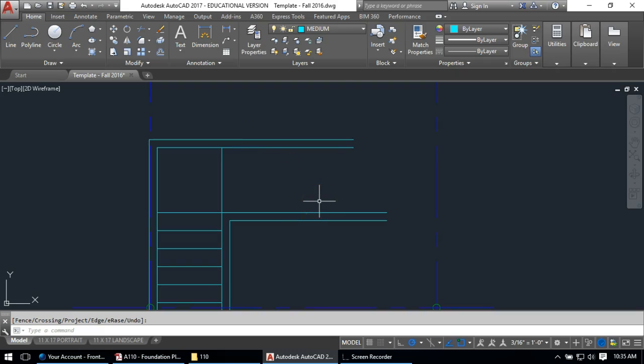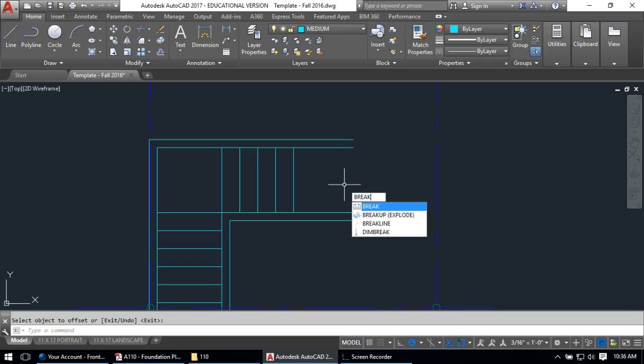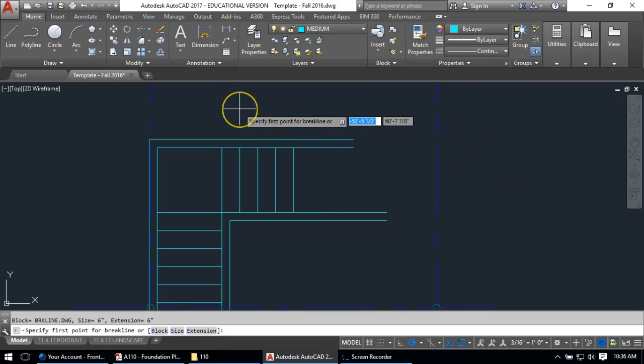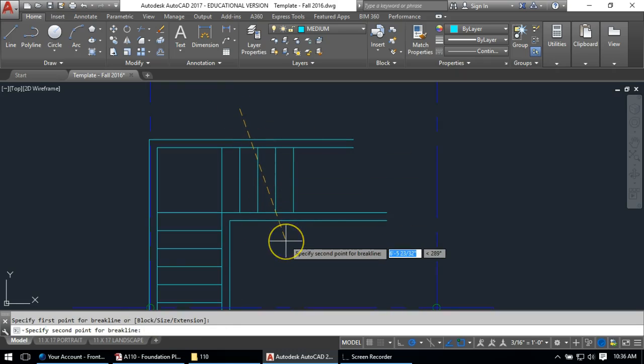I'm just going to offset a few because my break line might not be exactly the same orientation. So I'm going to offset the same 10 inches for the here. I'm going to get this long line here that I need to trim, just like I did below. Continued my same 10-inch offset. I'm just going to offset a couple over like this. And now I will draw my break line. There's an easy way to do a break line. I'm not exactly sure where the button is, so I'm just going to type in the command for you. It's break line. You can see it come up. The way you do this is I'm going to start at the top, and I'm going to draw a line, and it turns into this dotted line, and wherever I move it, it's going to draw a line.